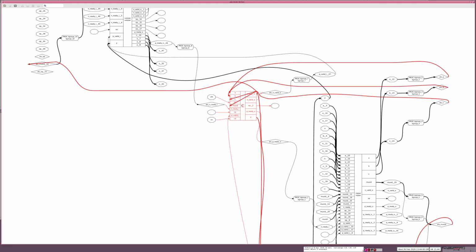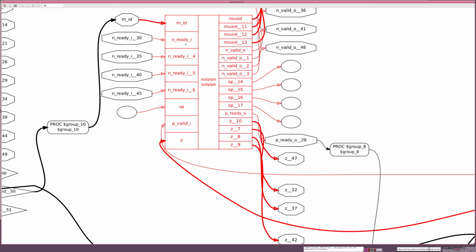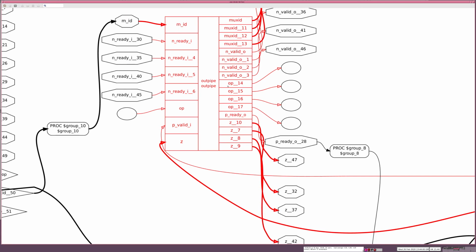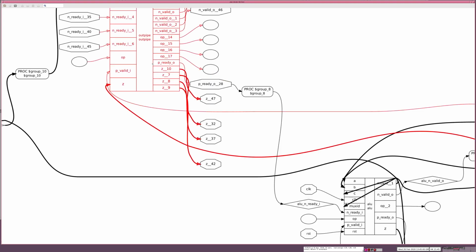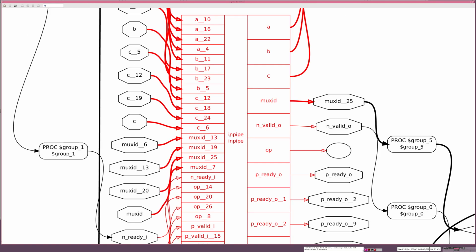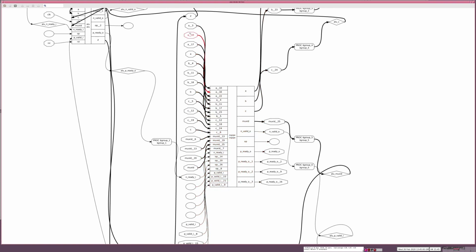Then it goes through the ALU, and a few cycles later it will be ready in the out pipe, and you will have the ready and the valid output, indicating when those valid O signals are ready. That says to the priority picker that manages the write register file data bus that the data is ready to be written, and can be selected depending on availability for writing into the register file. Or we will actually have register file bypass detection, and the data may go from here directly into another function unit in pipe, into one of these A0, A1, A2 or A3 inputs.